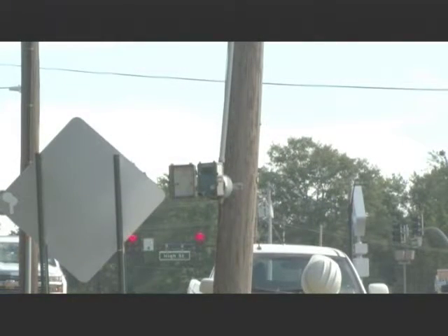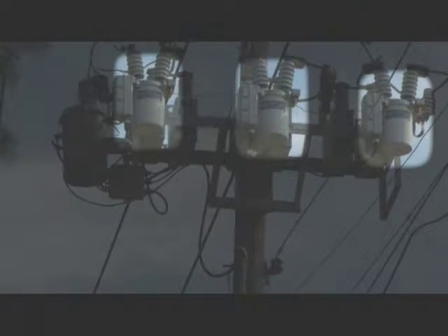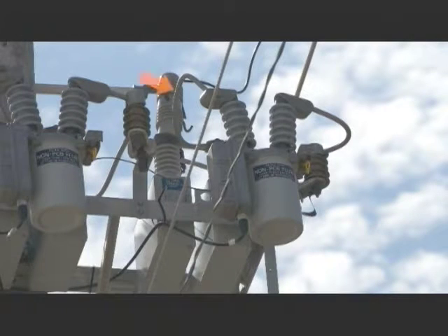The control mechanism is connected to oil switches through a control cable. The oil switches are mounted on the frame of the capacitor bank. A jumper from each phase is connected to one side of an oil switch, and the load side is connected to the capacitor bank with another jumper.